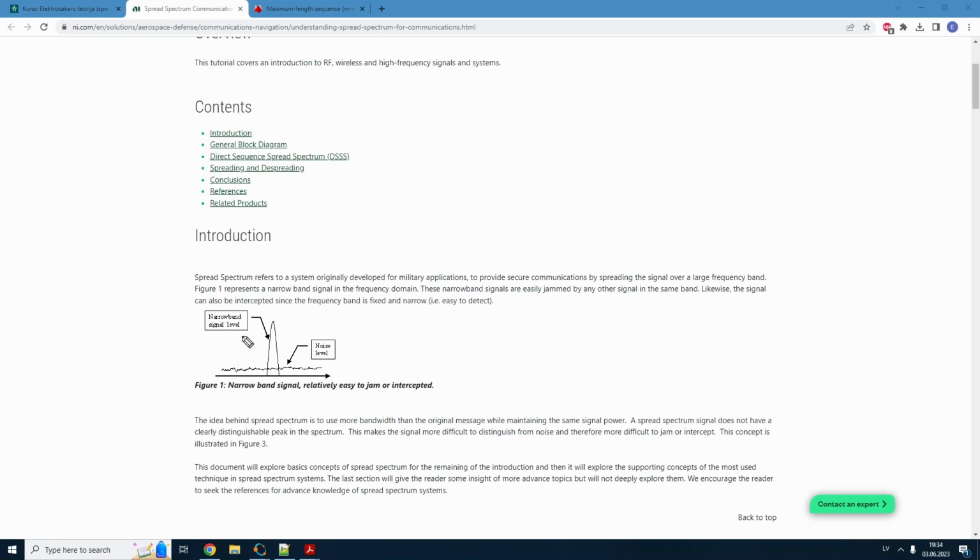What it actually does is this. Normally, we have some signal with some specific narrowband spectrum, which has specific energy. We then use different kinds of filters. We use some filters to separate frequencies, we use some filters to shape the pulses, and so on. But at any rate, we have noise outside of our useful signal spectrum, and we try to suppress all this noise as best as we can, because the noise power spectral density is in an infinitely large frequency range. This is a very small noise power N0, which we calculate in our simulations, but the bandwidth of this noise is infinitely large. So this is how we deal with it, by suppressing everything that is outside of our useful band. That is the normal transmission process.